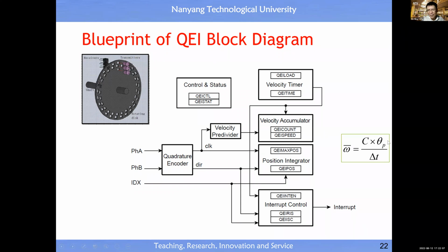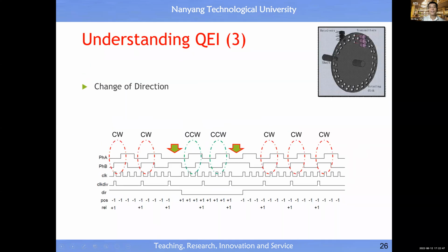Then next is to just get this count number, and get this value done already, because we cannot set this one. The sensor just outputs velocity per unit degree or per unit meter, per unit displacement, which can be angular displacement or linear displacement. Just consider this by default as 1. Once you implement it, based on your physical system, when you buy the digital sensor, the sensor will tell you what delta P is. Then you take this value times delta P, and you get the exact velocity. This is just for you to know.